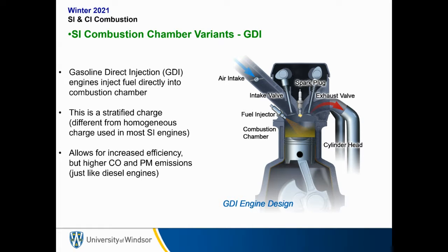They're going to use what's called gasoline direct injection. So instead of multi-point fuel injection, with the fuel injectors in the intake manifold spraying at the back of the intake valve, in gasoline direct injection the fuel injector sprays the fuel directly into the combustion chamber.